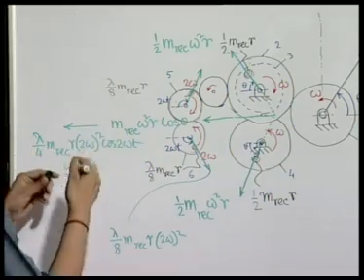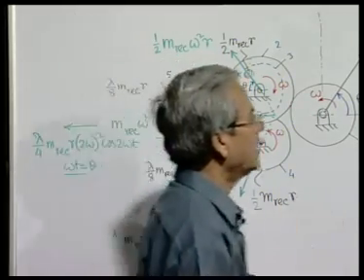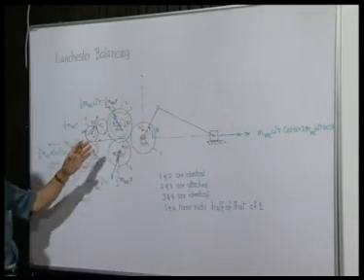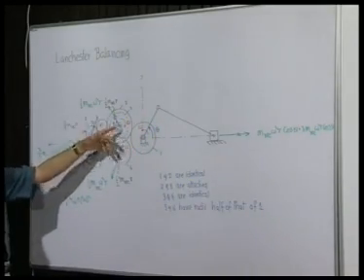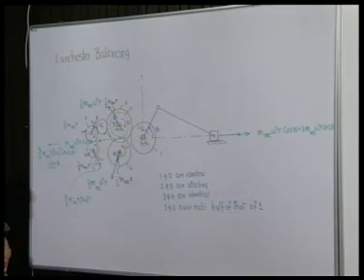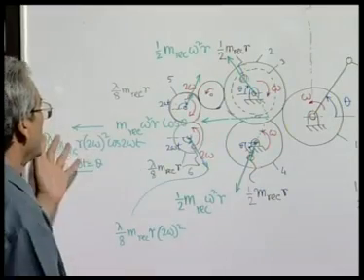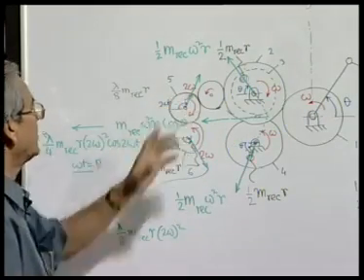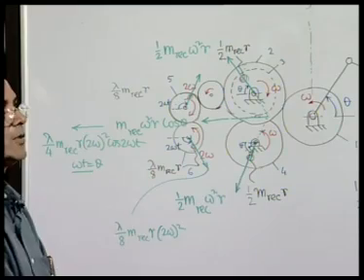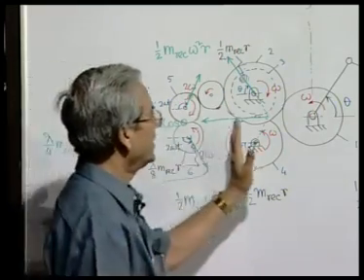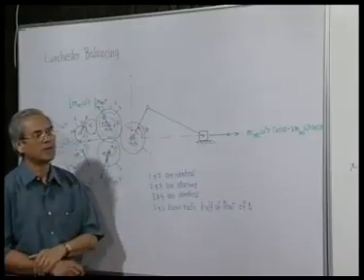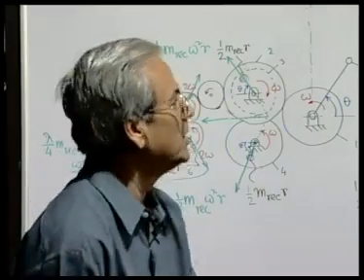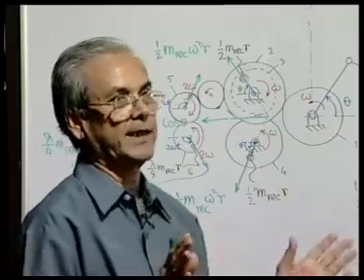So, this will again completely at every instant neutralize the secondary. So, the primary is being neutralized by this set of balanced masses, and the secondary is being balanced at every instant by this set of balanced masses. So, this way we can find that a complete balancing of the reciprocating unbalanced forces of a single cylinder machine can be achieved up to the secondary.